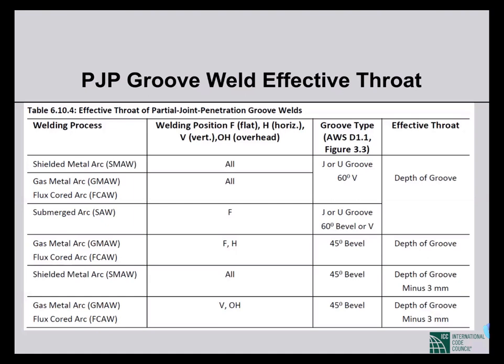So basically, at welding, shear is generated, and we have to multiply the shear strength with the area, then we'll get the capacity. So for that, we need to define the effective throat. Multiplied by the length is the effective area. So to determine the effective throat, we need to know what type of welding this is, what position of welding this is, and what the welding process is.